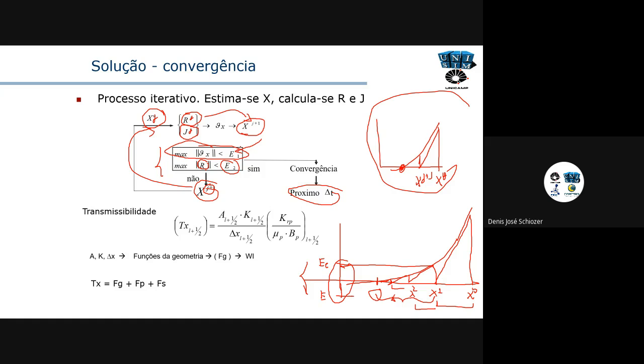If I want a very fast convergence rate, I can take this out. For example, if I have a lot of uncertainties in the reservoir, and I'm interested just in an initial solution and I don't need a very robust solution, I can take this equation out of the tolerance. Then I'm going to get a solution faster because only the second one has to converge, but the solution will not be very good. The residual will not be very good, but the solution is faster.